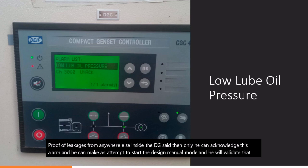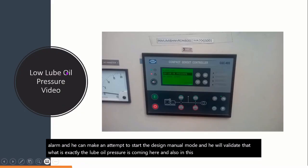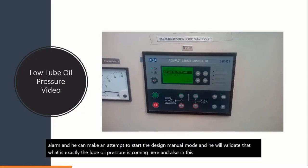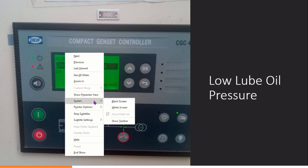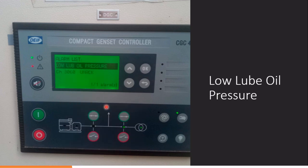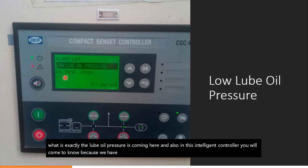And also in this intelligent controller you will come to know, because we have two different sources of alarm, one from the digital and the other from the analog, like we have seen earlier also. So we know that there are two different channels. Here the code will appear on the screen, and that code will tell us whether this is from the digital switch or from the analog sensor. Here we can see that the code number is 3060.